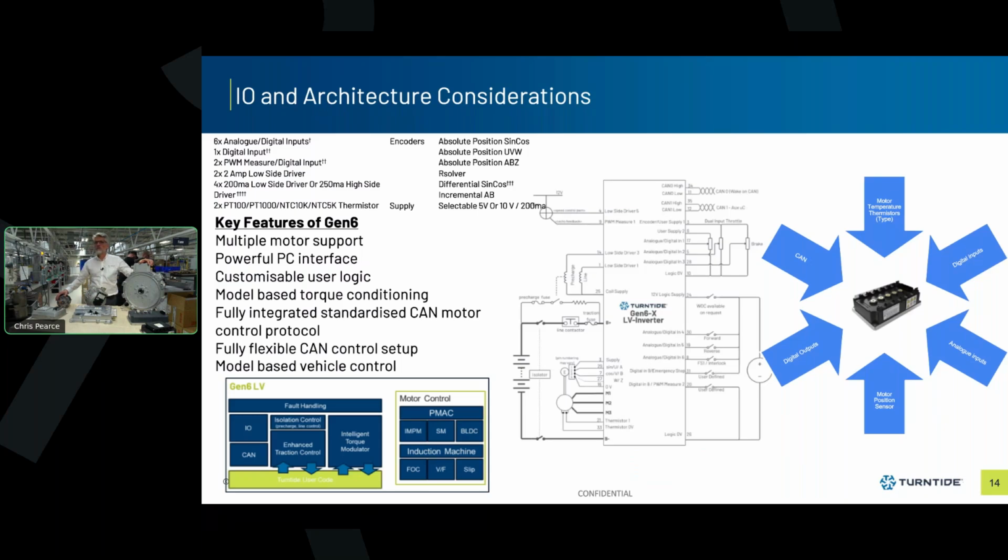And this product can be used in a number of ways. It can be driven as a CAN auxiliary torque actuator via CAN, using a standardized control protocol, which we call H protocol. That allows us to set points of torque, DC link current limits for driving and braking, torque limits for